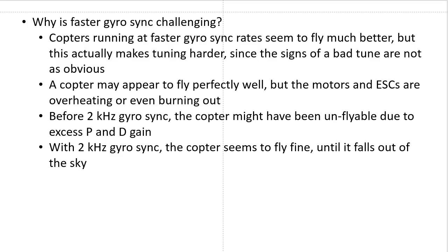And those micro oscillations coming out of the PID loop wouldn't have been there if the PID loop was running slower, because these high frequency components would have been filtered out by the aliasing. They would have been converted to low frequency components by aliasing, and that would make your copter fly worse, but it wouldn't destroy your motors. Now that we're sampling accurately, we are actually seeing these high frequency components, and the PID loop is trying to deal with them, and the motors are freaking out and burning out, and the ESCs are burning out.